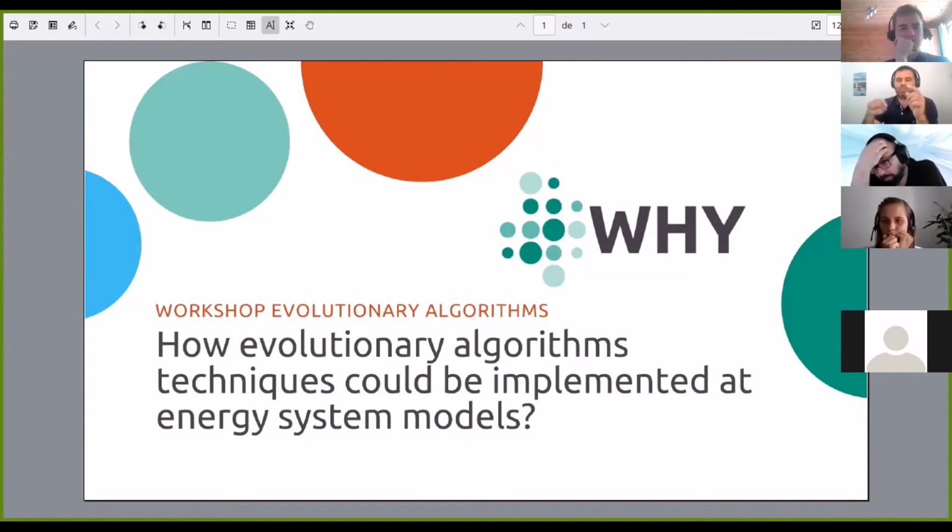Traditional controls just put set points. The control temperature is this one, the amount of water is that amount, and I don't remember the other one. And those are fixed at the start. The process goes in continuous mode until the catalytic is destroyed. This is the traditional way. And we put a neural network there that controls the 3 of them dynamically in order to avoid the deactivation of the catalytics. And we have double the yield of the system in simulation.